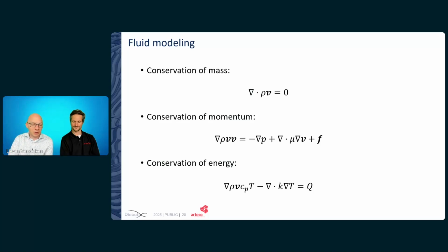What I most wanted to highlight are the 4 key parameters that quantify a coolant from a thermal perspective: the density, the viscosity, the conductivity, and the heat capacity. They all have a direct impact on the conservation laws. You can see, for instance, in the conservation of momentum equation, the direct link between the viscosity and the pressure drop.